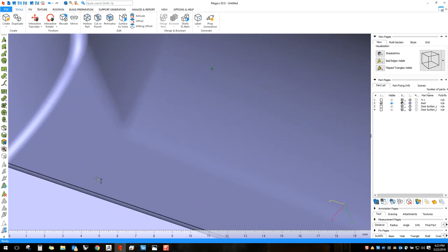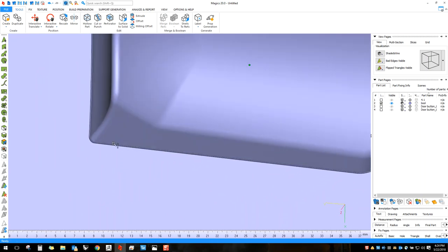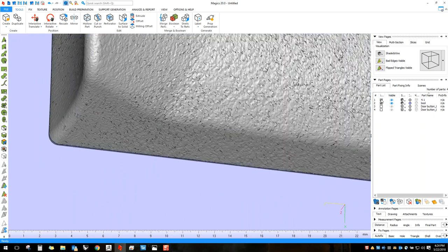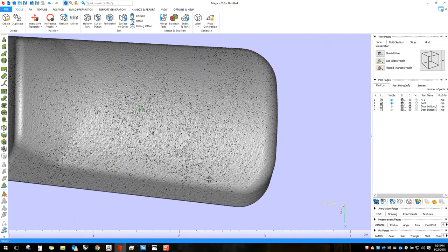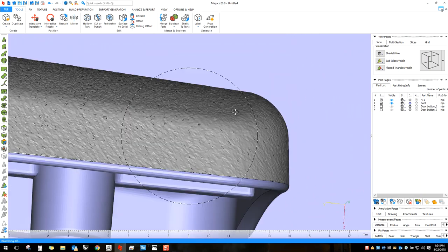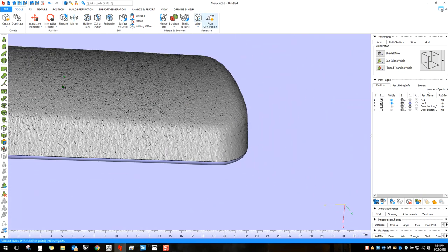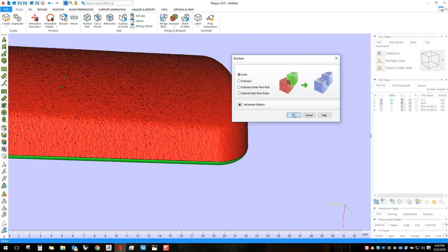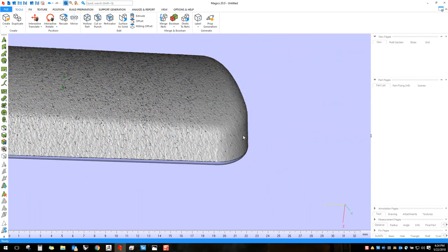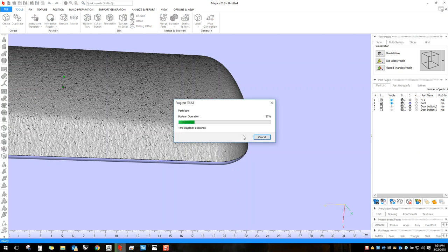So now we've got this little lip that runs around the outside, which is slightly smaller, just enough space for our textures to fit in there. And so now that the textures are perfectly overlaid, it's very simple. You just go Boolean unite, click OK, and then they should fuse together perfectly. A lot of times I'll fix it after this, but that's totally up to you. And that's basically how you texture parts using this particular workflow.